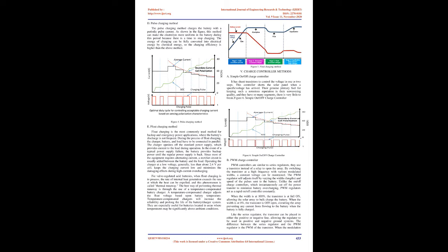Another main difference between NiCd and NiMH is that NiMH offers higher energy density than NiCd. In other words, the capacity of a NiMH is approximately twice the capacity of its NiCd counterpart. What this means for you is increased runtime from the battery with no additional bulk or weight. It can store 100 watt-hours per kg. They are more thermally stable than lithium-ion batteries. The self-discharge is higher than the other batteries.